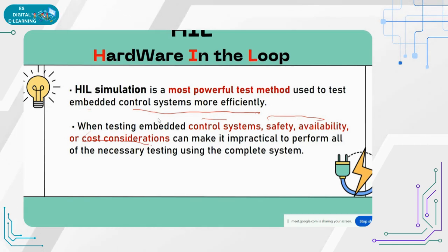In HIL we have the simulation. Simulation is an application where we can create the vehicle model, and the person can be put into the car and drive, and he can see whether the braking condition in the software and the ECU is working fine. Just by driving the vehicle it can be verified. If braking did not happen, that can be debugged, identified and fixed very quickly on the HIL, but in the real vehicle that is not possible.